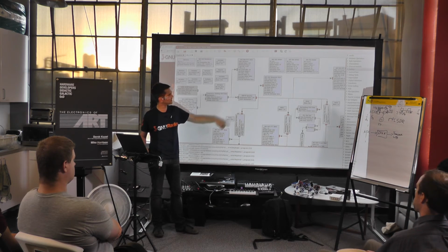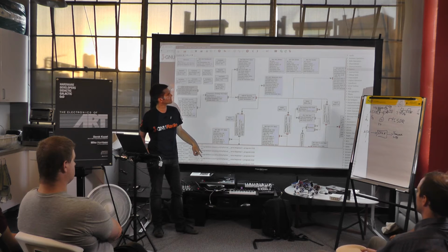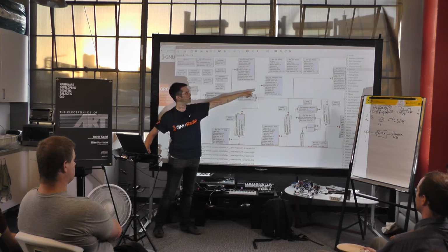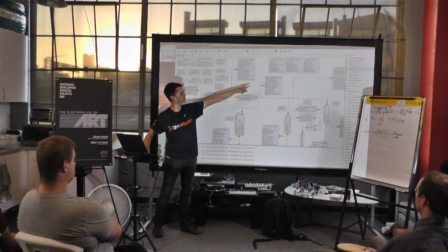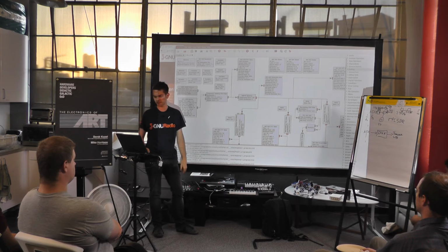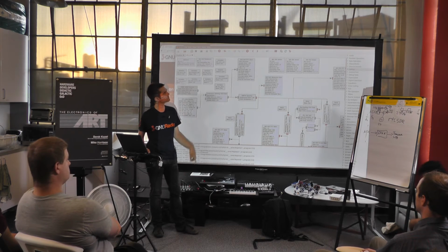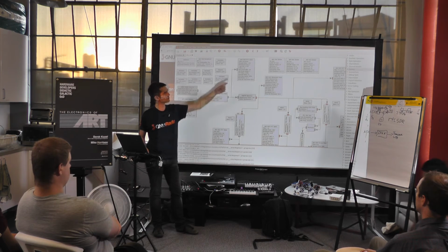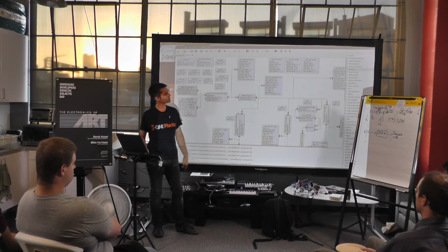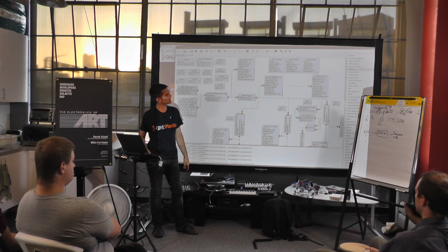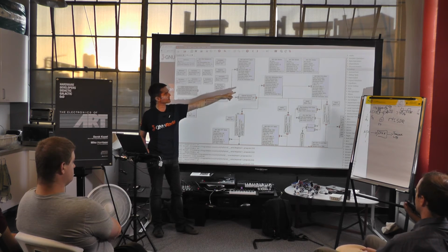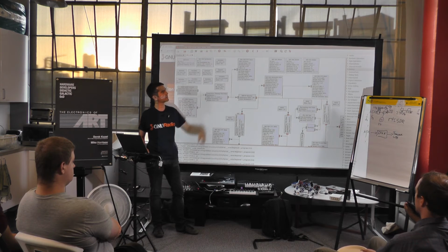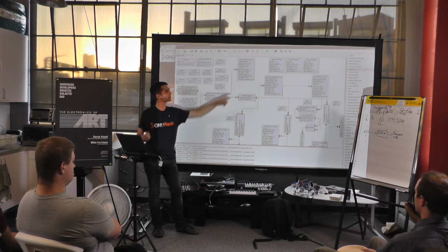Then it gets demodulated. This, I believe, oh no. And so it gets demodulated, and you get another waterfall sink that says waterfall plot. And so that was the final tab on that previous one. We have 3 sliders again, one for gain, one for frequency, one for volume. I can drag this in. There's another frequency sink, fast Fourier transform sink. So we're seeing the spectrum, and this is of the FM demod. So that's the actual audio spectrum that you see.